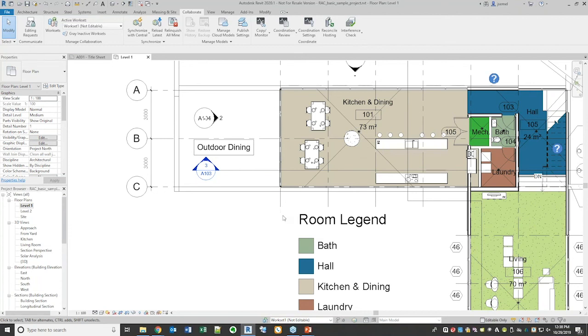So when I do the sync with Central, a few things are happening. One is that it's sending my changes to the authoritative copy in the cloud, which is at Amazon S3 servers. In the background, all the other computers that are on this project and have worked on this model are going to download all the changes. So that's going on in the background. So when I hit Sync with Central, it's also going to incorporate all the latest changes that are from all the other nodes. And that way I get everything, and everything works in real time.